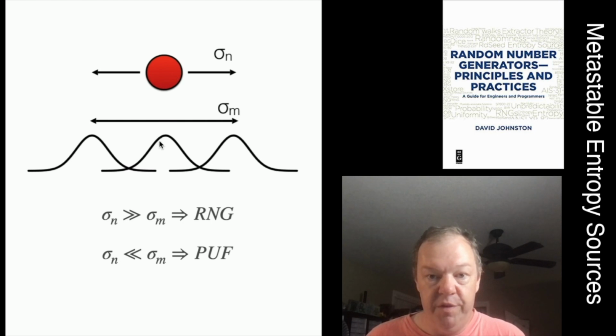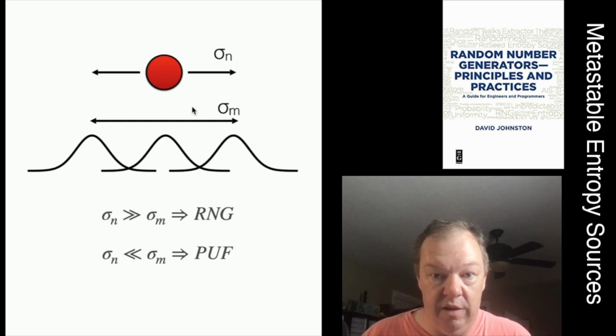Then the position of the hill is going to determine whether you get a 1 or a 0, and that's always the same position in the same bit of silicon. And so you'll get a random bit as a function of what the bias in the circuit or the position of the hill ended up being. You could turn the circuit on and off and on and off, and it would always produce the same bit, and that's what we'd call a physically unclonable function. And I won't go into more on PUFs, that's for a later time, but we have these requirements.